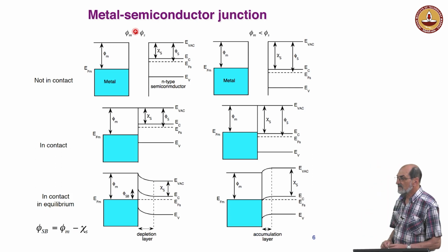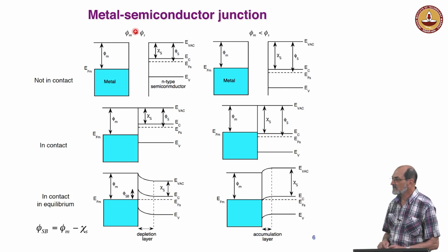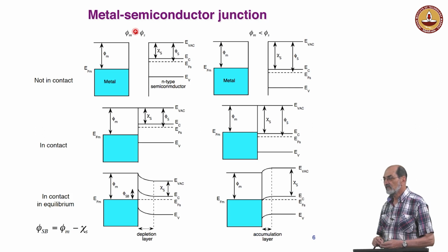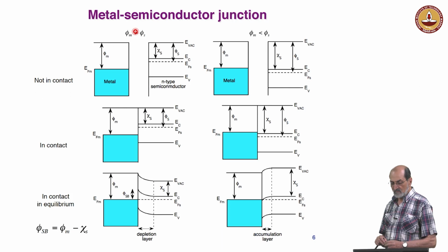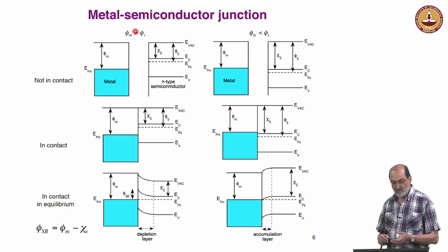Well, there are tons of books and papers written about that. People essentially, I think that so far people do not agree. People talk of dipoles forming at the interface, for example, the famous MIGS, metal-induced gap states, and things like that. But interestingly, as the semiconductor has a more covalent character, the less response to these rules.